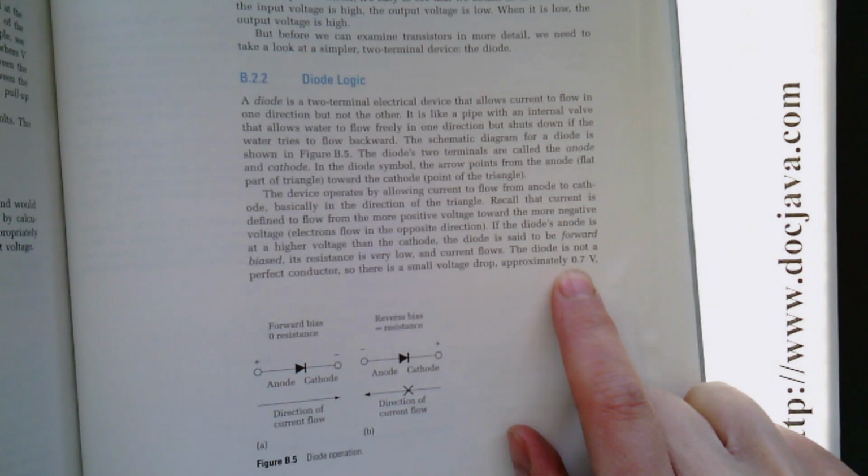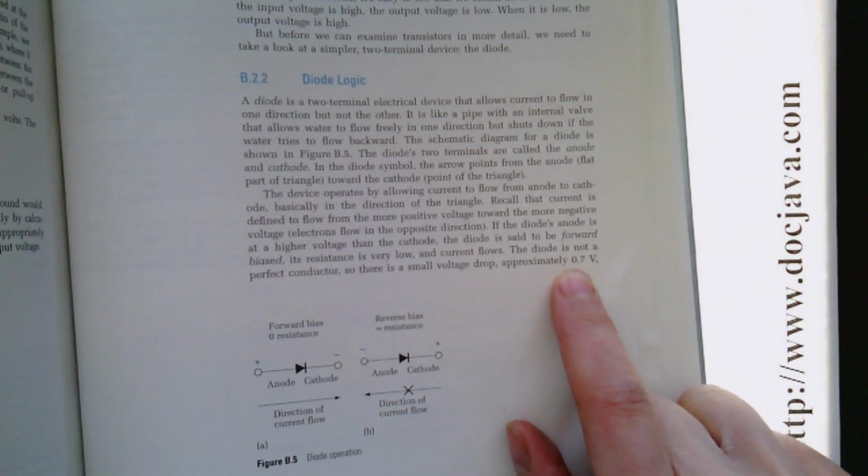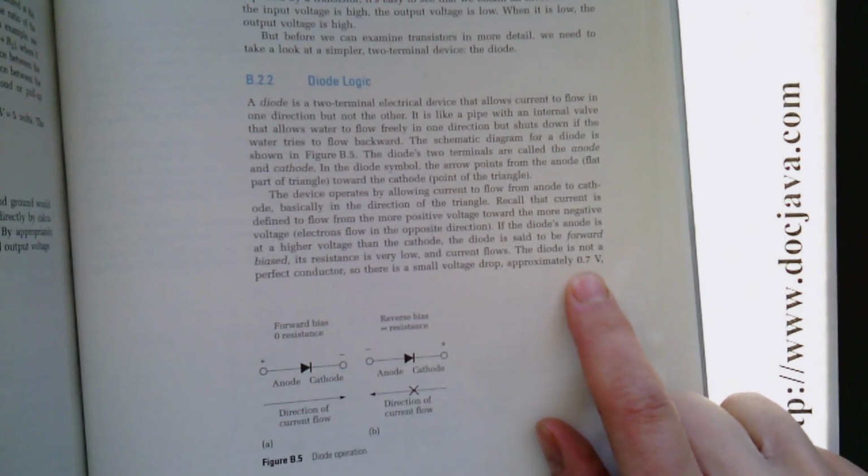Ohm's law, right? Voltage drop E equals IR. Or P equals IE, that's even worse. So the power with 10 amps and a voltage drop of 7/10 of a volt, now you've got 7 watts that you have to dissipate inside the diode, which could burn it out if you don't have a way to heat sink. Sink the heat. Heat the sink? Yeah, heat the sink. Sink the heat.